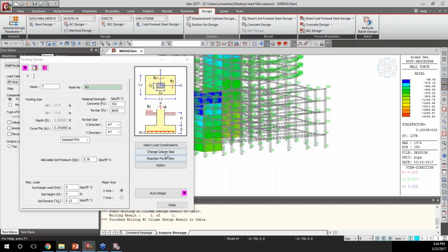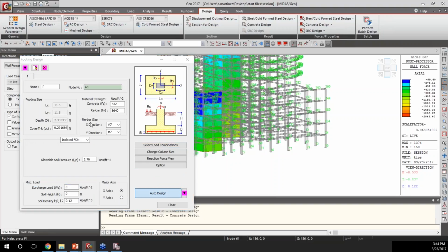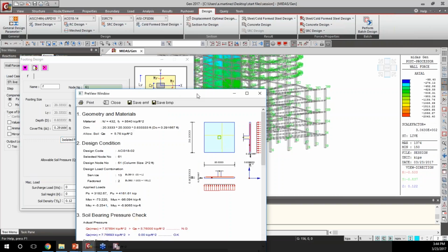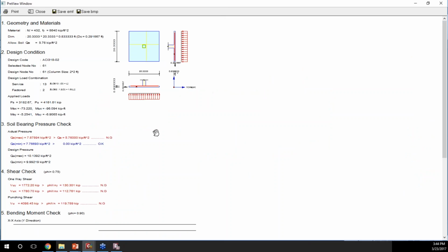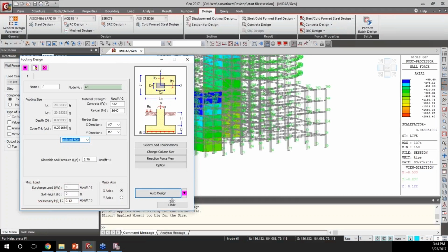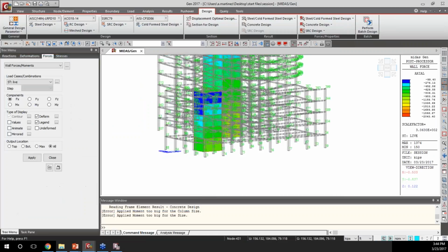We can give it some information about the load combinations, or you select which node combinations you want, and you can tell it some information about the rebar, and you can do, again, similar to what we had done before, like first a test, a code check. So we're seeing here we're not passing. And so you can go back and give it information about what rebars to consider, and then try to get it to design the reinforcement of it. But suppose that all that fails, but what if you just wanted to get the optimal size for your load?